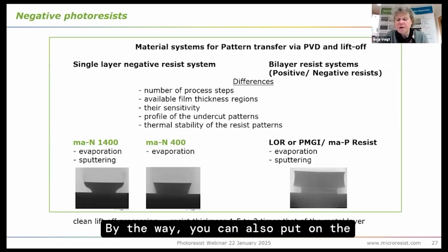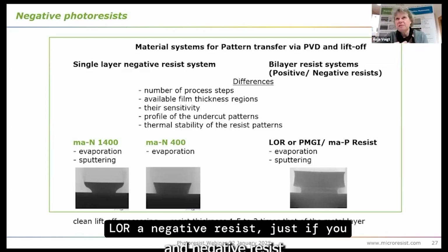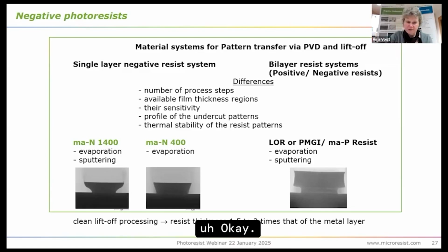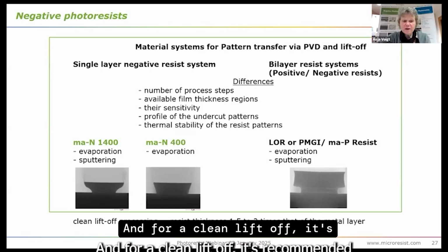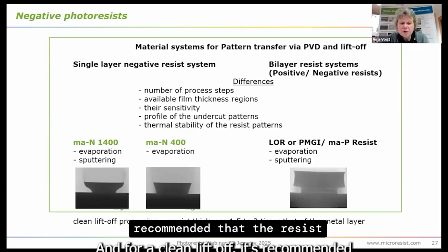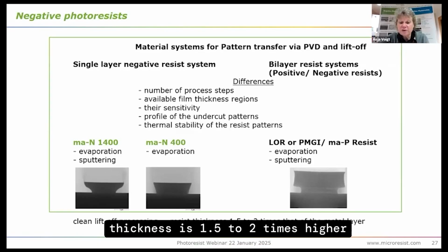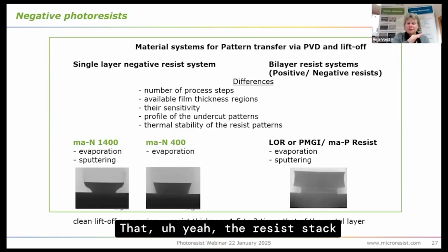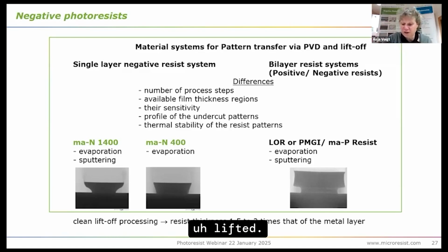By the way, you can also put on the LOR a negative resist, just if you have a negative tone mask. Okay. And for clean lift off, it's recommended that the resist thickness is 1.5 to 2 times higher or thicker than the generated metal layer. That the resist stack with the metal on top is clearly lifted.